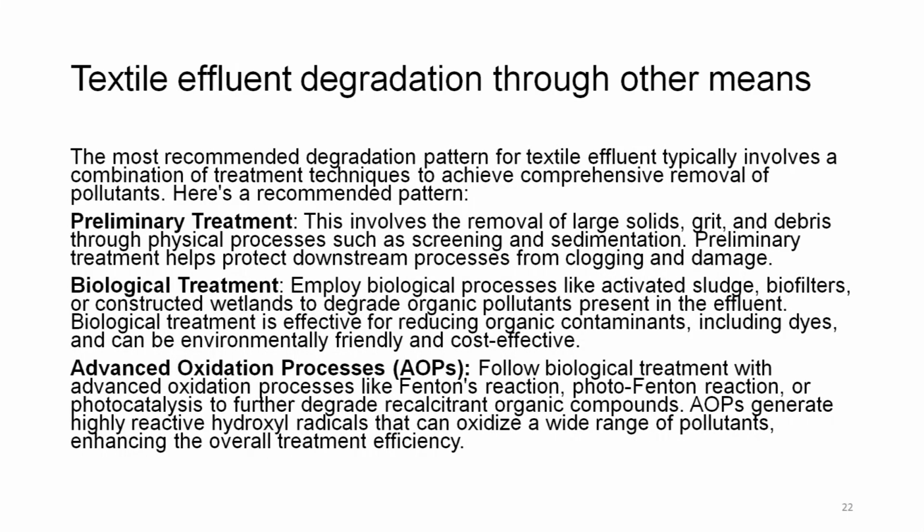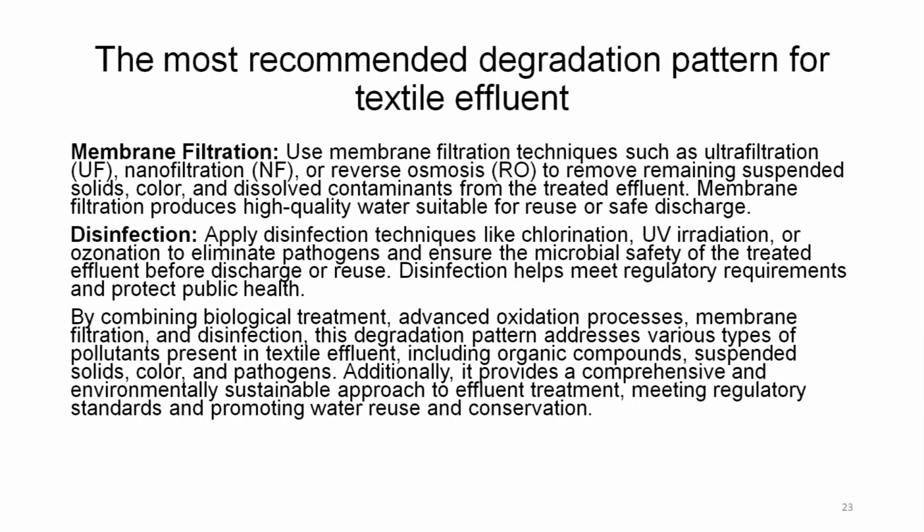Advanced oxidation processes, AOPs, follow biological treatment, with processes like Fenton's reaction, photo-Fenton's reaction or photocatalysis to further degrade recalcitrant organic compounds. AOPs generate highly reactive hydroxyl radicals that can oxidize a wide range of pollutants, enhancing the overall treatment efficiency. Membrane technology and membrane filtration we have studied quite in detail; membrane filtration produces high quality water suitable for reuse and safe discharge.